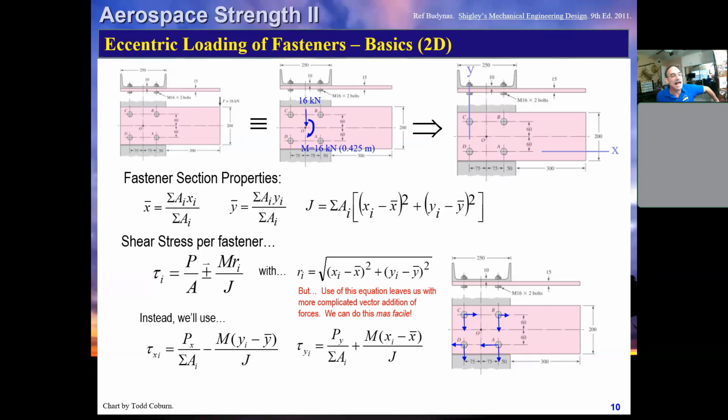You'll notice here we have an X and a Y component shown. Let me do that again. This first equation gives us the X component, and it looks like this. You'll notice they're going different directions because we have both the axial load and the moment accounted for. We're getting the horizontal component of stress due to the axial force, if there's one in the x direction, or minus x. And we have the x component of the stress due to the moment.